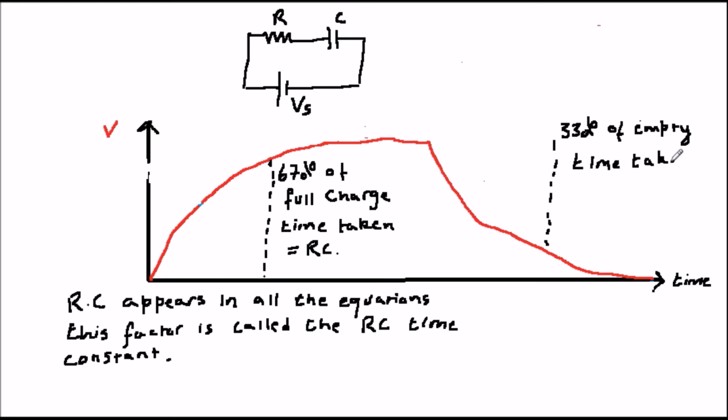This gives us a clue to the purpose of capacitors in DC circuits. They are often used to provide timing and delays by devising circuits which trigger once they have charged up to a set value. A very popular integrated circuit, that is a silicon chip, which uses this principle to generate all sorts of useful timing signals and waveforms, is called the 555.